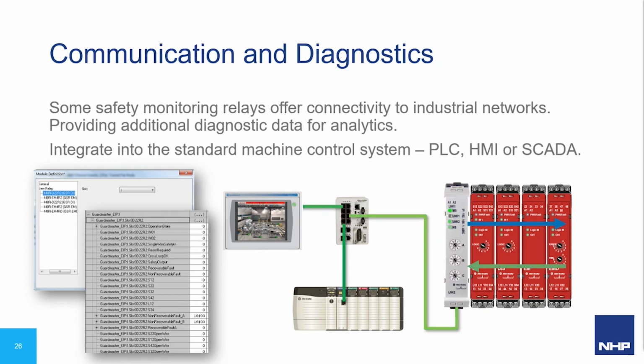It can also be used to increase non-safety diagnostics, which allows us to gain as much information as possible from individual field devices. The level of diagnostics no longer only just points to where on the machine a problem exists, but has increased to the point of providing detailed fault codes and suggested remedies. Ultimately, the non-safety communications and diagnostics can help minimize unplanned downtime and increase overall efficiency, all from a smart safety monitoring relay.